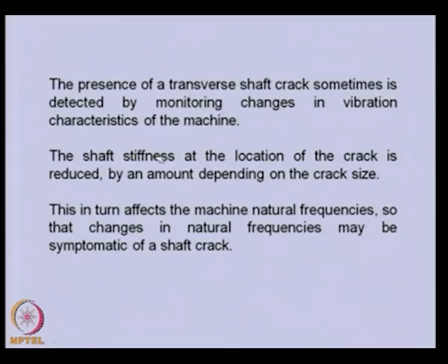The shaft stiffness at the location of the crack is reduced by an amount depending upon the crack size. That in turn affects the machine natural frequency, so changes in the natural frequency could be a symptom of the shaft crack, because the crack introduces flexibility in the shaft that changes the stiffness, and natural frequency is nothing but root k by m. So, if stiffness changes, we expect there will be a change in the natural frequency of the system.